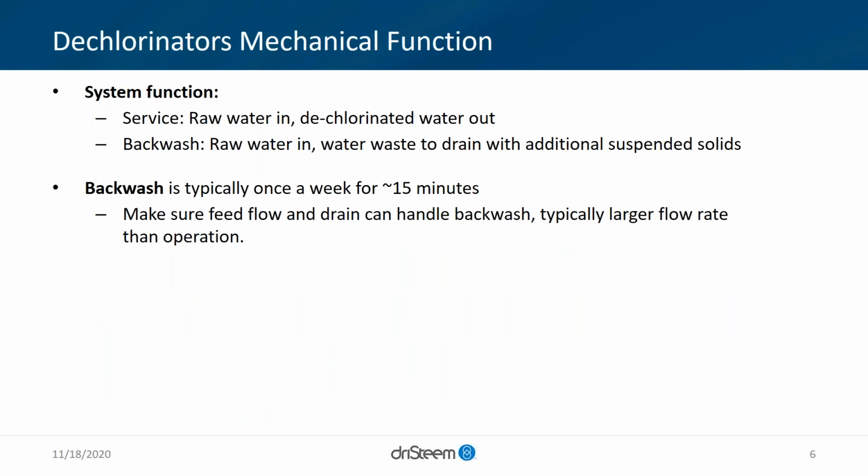Again, brief description of the function. This is a lot simpler than a softener. Regarding our offering, during service, raw water comes in, goes through the control head, which I'll show in a moment, down through the activated carbon bed, and collected and brought back up through a clean water tube. I forget, as we're doing these webinars, you guys can't see me, in quotes, clean water. Obviously, it's only really functioning on the chlorine aspect of things and doesn't remove other, let's say, inorganic dissolved solids.